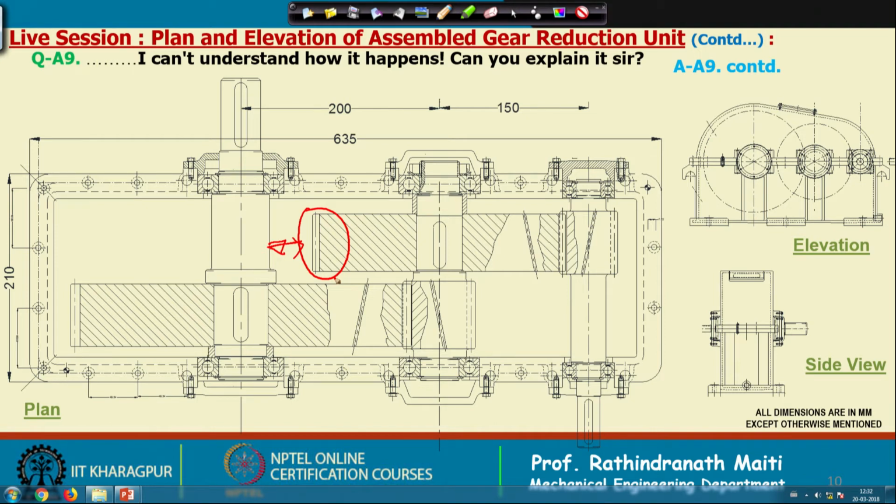The best design is that here about 10 millimeter gap. Once you have selected the gear size, that cannot be found out automatically. You have to design the gearbox and then you have to see, maybe 2-3 trials will be required, or you can use an optimization tool by which you can find that. Okay.